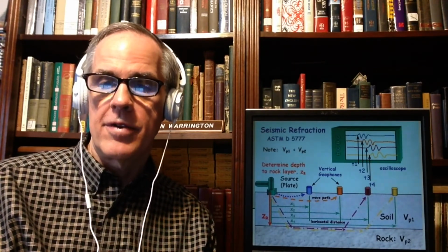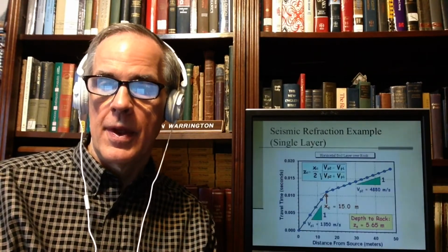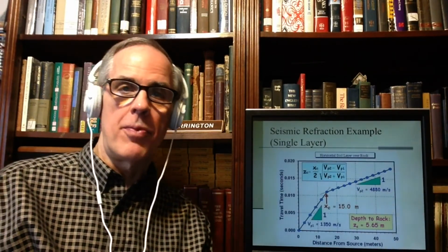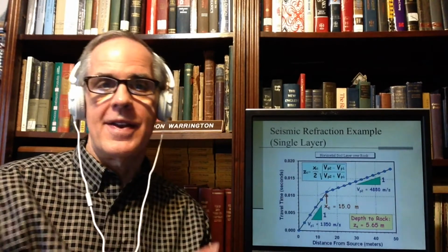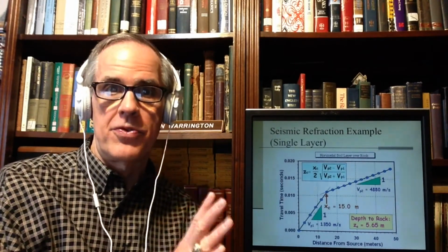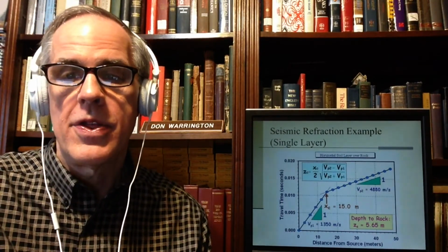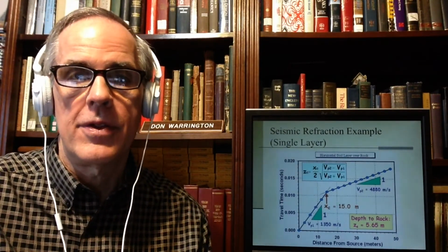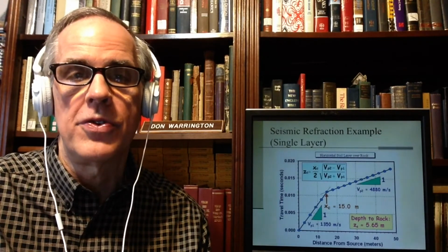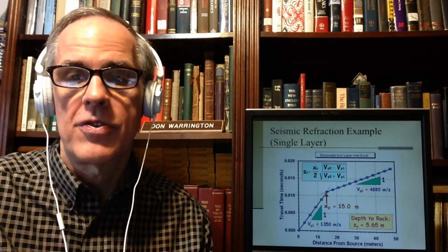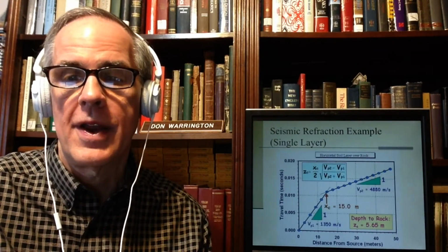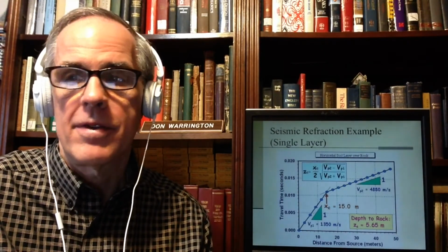If the wave path is short enough, it goes directly, like the blue and orange ones do. Whereas if it's reflected, it does like the purple and yellow ones do. And when you get to the purple and yellow point, that far away, you get a knee in the curve, and that's just for a simple soil profile. Then, if you know the sonic velocities of those two layers, you can actually use this simple formula to get an estimate on how deep it is.